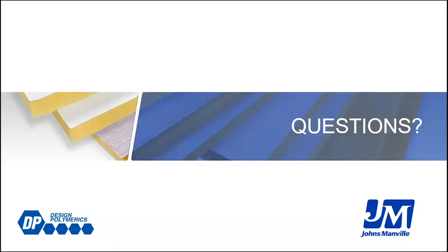The adhesive in those duct tapes becomes brittle with temperature cycling, which is exactly what a duct system does. So the international energy codes are in the process, and have been in the process, of not allowing duct tape as a duct sealer.